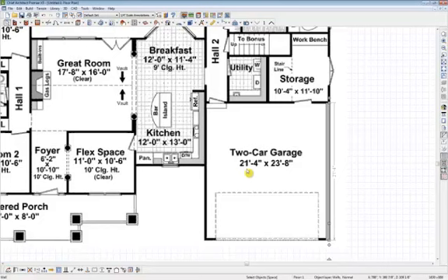In this instance, it's a little bit smaller. Whereas the dimension in our image says that this needs to be a 23-foot 8-inch wall, we have a 21-foot 4-inch wall. So, one of our options would be to select the image and use the edit handles to manually resize this image until that wall's measurement is accurate.